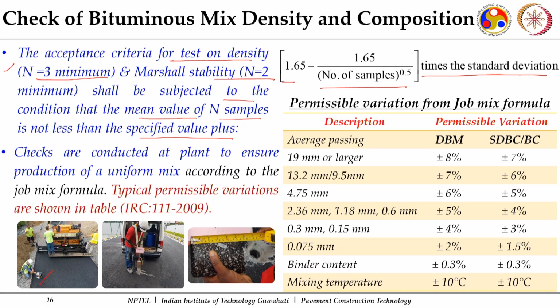Now what I can do with nuclear density gauge, with these density gauges, I can cut down a core, I can determine the density of these mixes in the laboratory by different methods. We have water displacement methods, some vacuum sealing methods which can give us the density of these. So then I can ensure whether with this density it is meeting the requirement for the amount of compaction which is required.